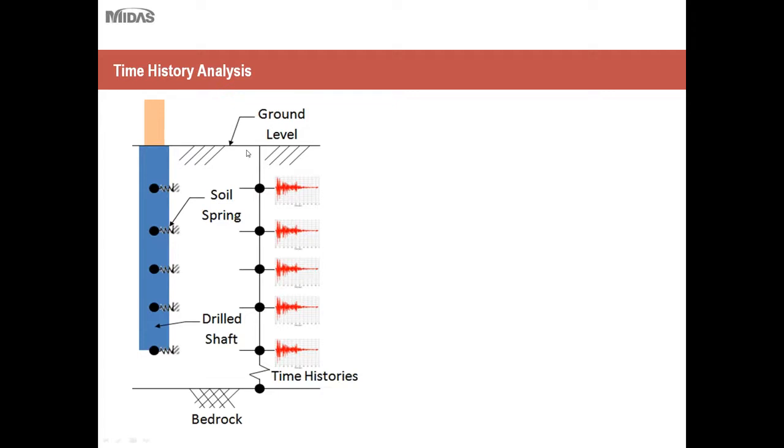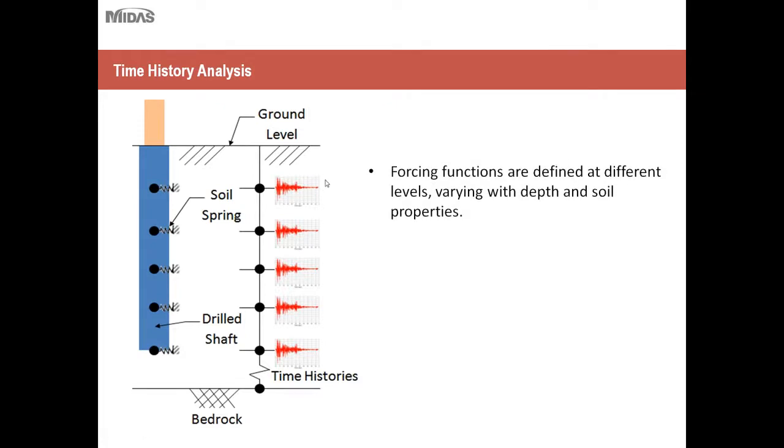Something very unique about seismic analysis in general is the use of soil springs, and forcing functions as well. Here we have an example of a driven shaft pile or a drilled shaft, and here we have several soil springs modeled on these nodes.